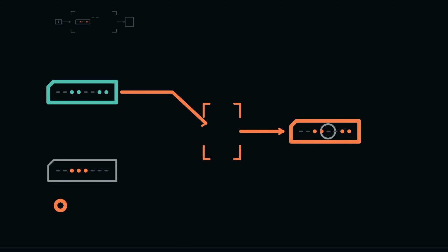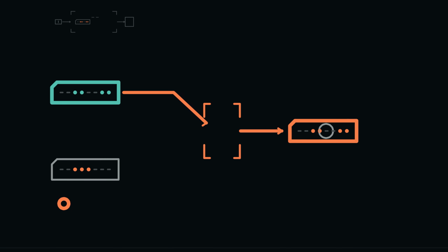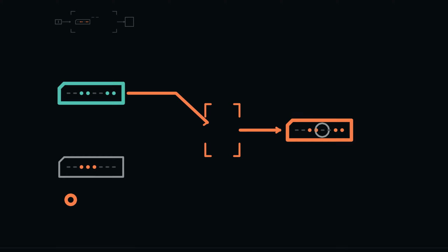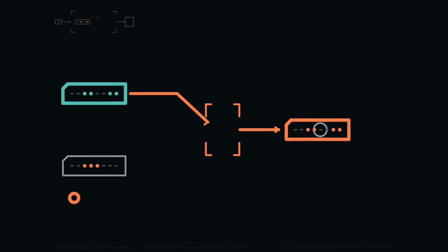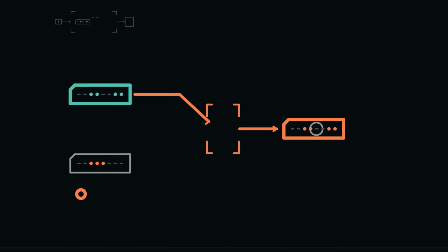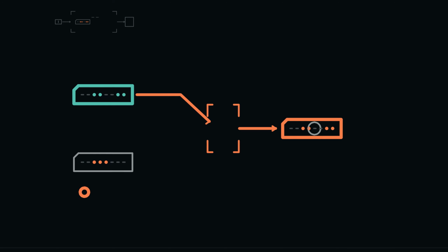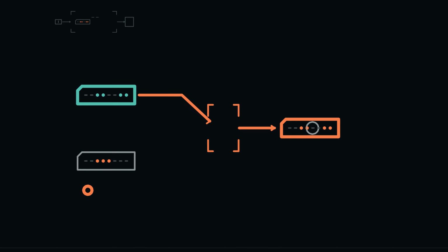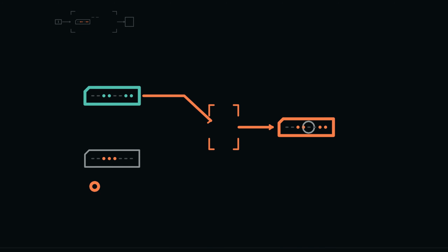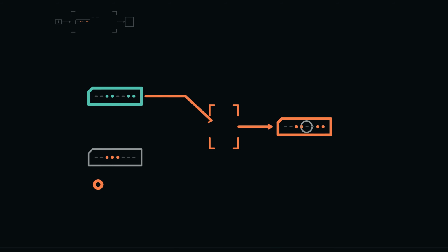Build the other path by ANDing select directly with B. When select is 1, this path passes B. When select is 0, it is forced to 0. Finally, OR the 2 path results. The complete relation is: not select and A, or select and B. For either allowed select value, exactly one data path can affect the output. The other contributes 0 to the OR, and therefore cannot alter the selected result.